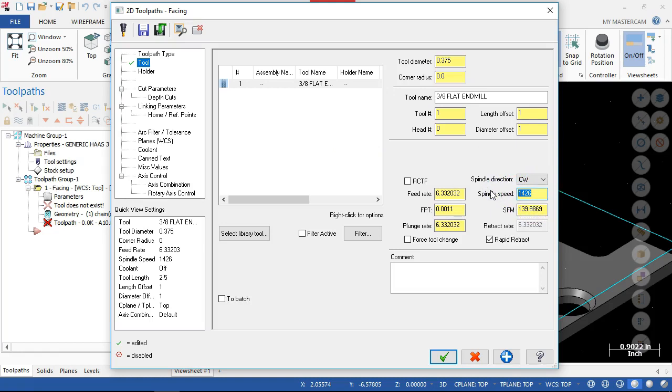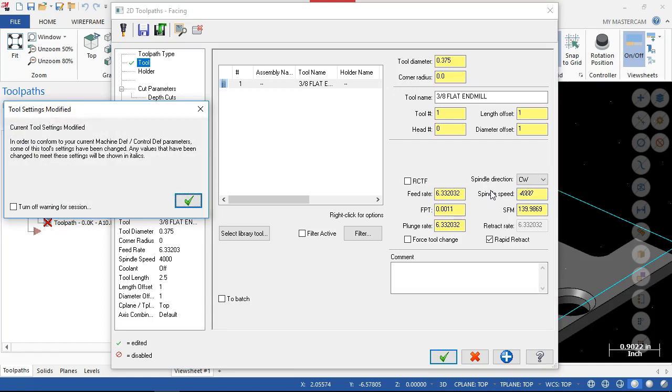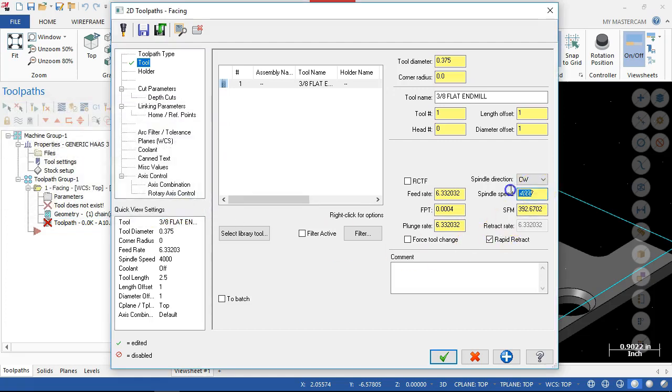So let's see if it'll, all right, since I set this up to run on the TM 4,000 RPM spindle, it's warning me that if I put anything over 4,000, and that's kind of an error checking depending on what machine you're programming to. All right, so I can enter 4,000, but 4,001 is going to have that warning associated with it. All right, so I'm going to give it 2,000 and, per tooth, nah, 32 is a little fast. 16 I can live with, and maybe